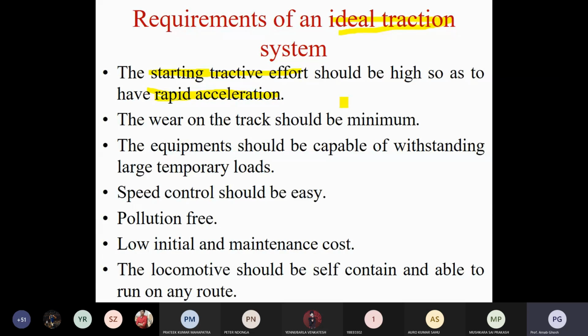So the tacho generator senses the speed and converts it into voltage. In the differential amplifier, we are comparing the actual speed and the rated speed. Your actual speed, after the tacho generator, is now in the form of voltage, so you should put the equivalent voltage of your reference speed. Then we get the value of the error.